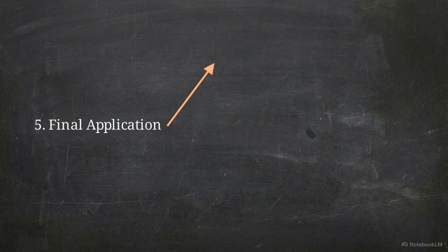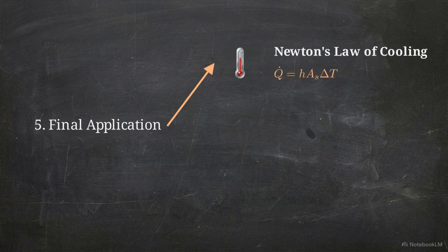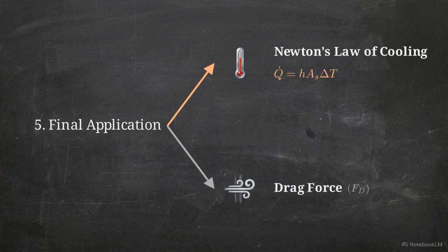Step 5 is application. We take that physical coefficient and plug it directly into Newton's law of cooling to find the final rate of heat transfer, or into our drag force equations to find the physical force acting on the surface.